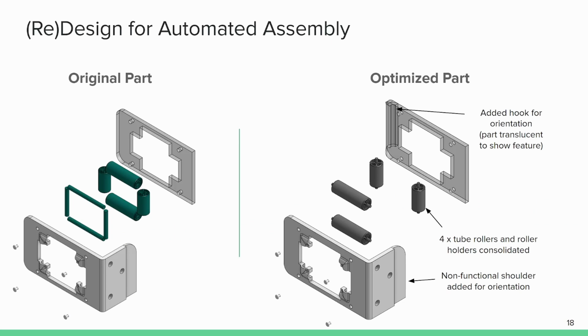The subassembly we selected, as mentioned previously, contains several small parts with, nonetheless, a high functional importance, such as the roller support and the tube rollers. According to the FCMM, these parts perform important functions, such as preventing kinks in the tube and allowing it to retract and protract smoothly. The redesign follows several important DFA considerations for automated assemblies, such as the fact that parts must be easily orientable, should be able to maintain their orientation as they're assembled, and must easily be oriented within a vibration table.